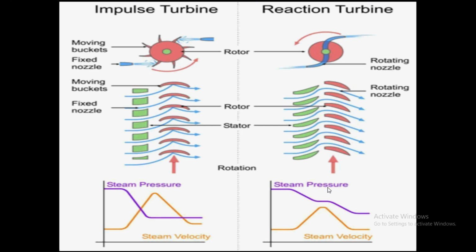Next is the turning gear. The turning gear is generally used with large turbines and consists of a gear integral with the turbine shaft driven by an electric motor through necessary speed reduction. The turning gear is used so as to keep the turbine shaft rotating at about 1 to 20 rpm in order to avoid springing of the shaft occurring due to unequal expansions and contractions during warming and cooling of the turbine.